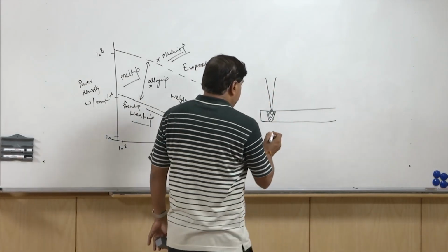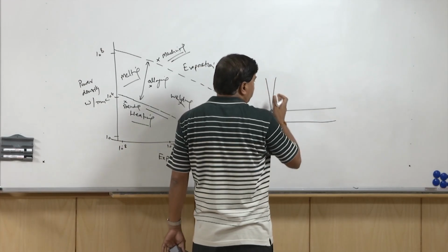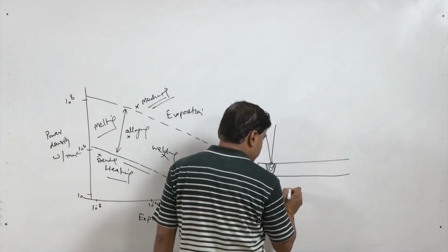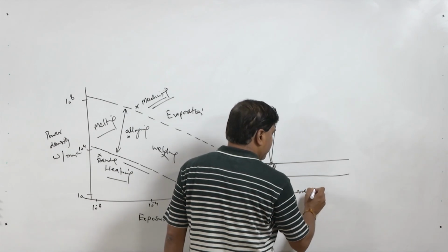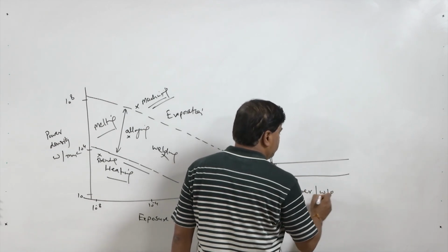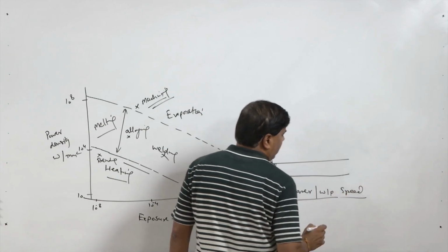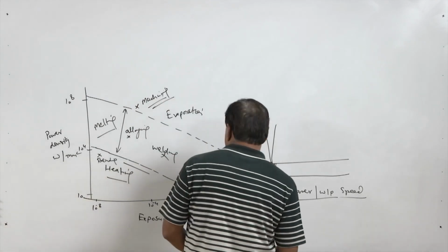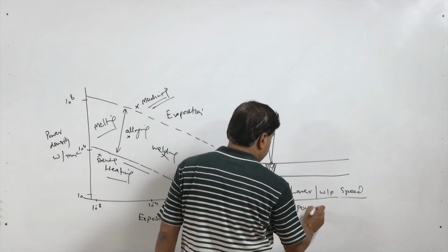The speed of the relative movement between the laser and the workpiece is determined using suitable values. So you can say the laser or workpiece speed, whatever is used, will help us in determining how much energy is being delivered per unit length, and the power of the laser certainly matters.